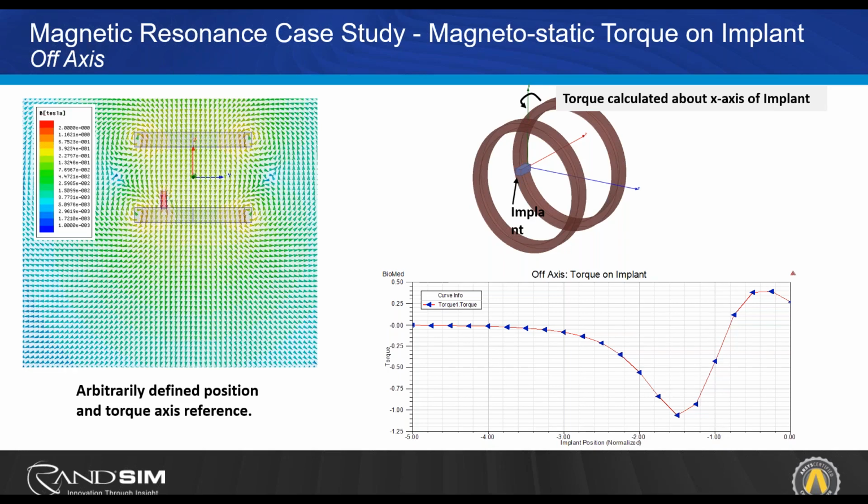And by changing those values, you're going to see a change in your parameters as well as your fields. What I think is really interesting about these tools is you can do this in real time. So I can change a capacitor value or a host of capacitor values, let's say from 4.5 nanofarad, I can change those values to 5 nanofarads, 10 nanofarads, whatever, and you'll see that effect in your results. And for an electrical engineer, this is really nice because with a lot of tools, when I'm doing these simulations, if I make small changes to my design, it's traditionally going to cause me to resimulate, which is time lost.